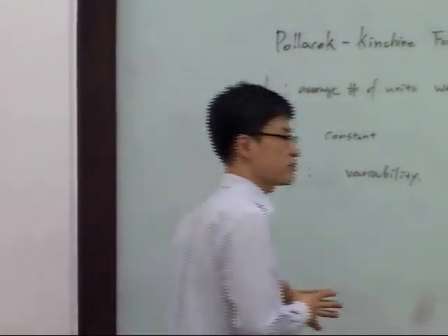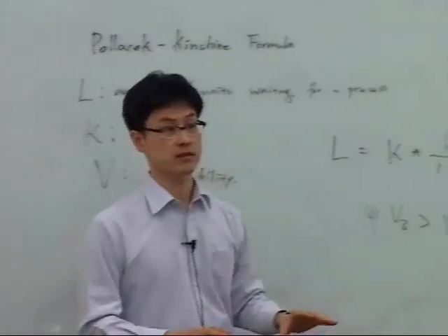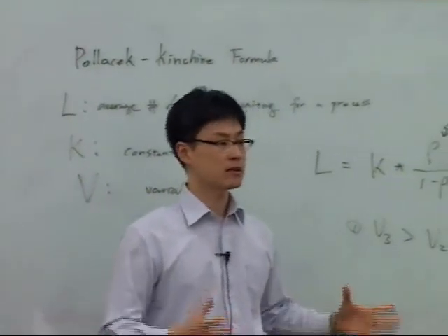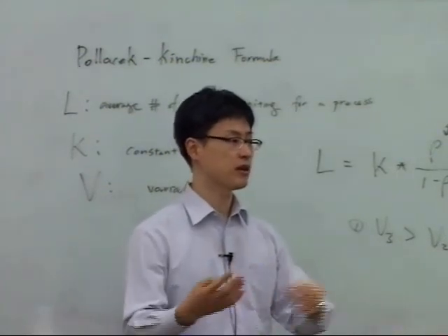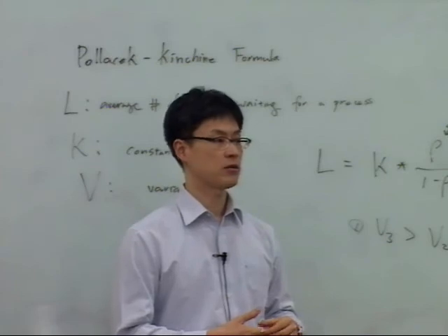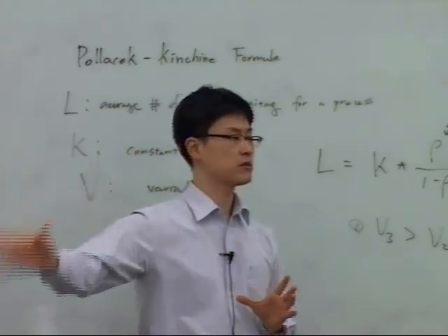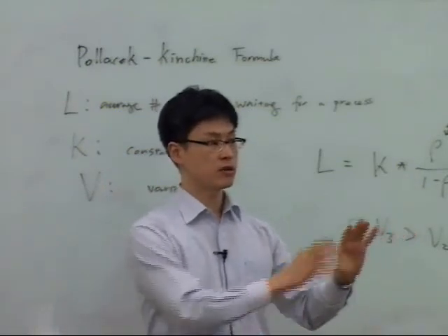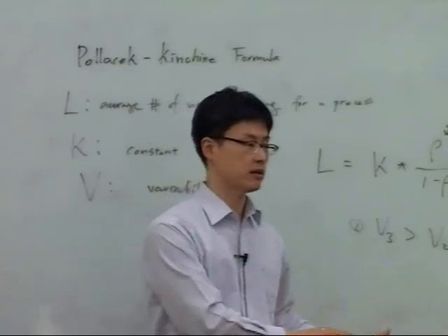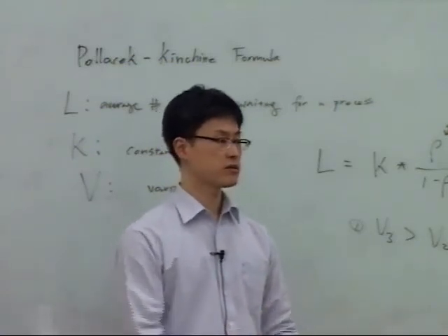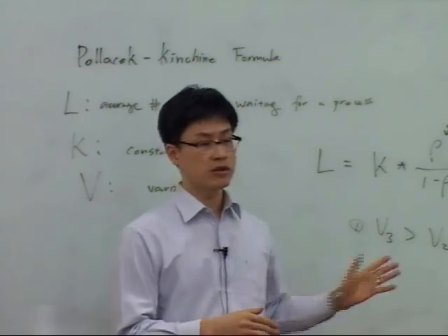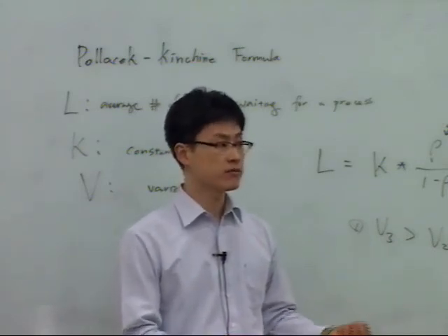In today's class, we just briefly discussed the very basics of factory physics. Everything is based on this rule. And with this tool, you can easily design a simple factory based on the utilization, throughput, and capacity. Based on this, people actually design a factory. They have a plan: we'd like to make this much of this product, and there is some machine with this capacity. In order to make this much of the product, throughput should be like that. Then you can assign workstations and routings and everything. This is called capacity planning at a basic level. So with this knowledge, you can actually design a very simple factory.